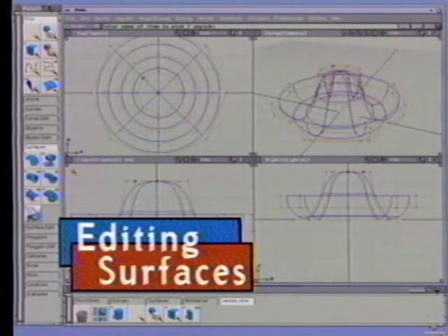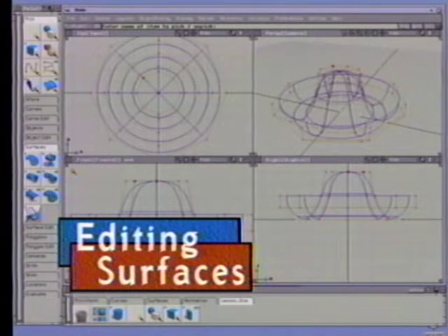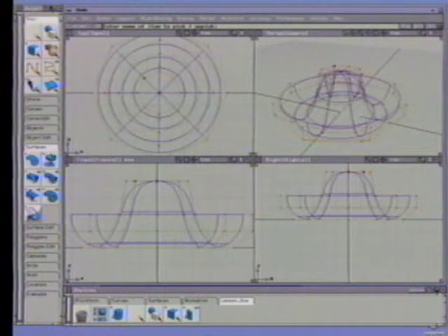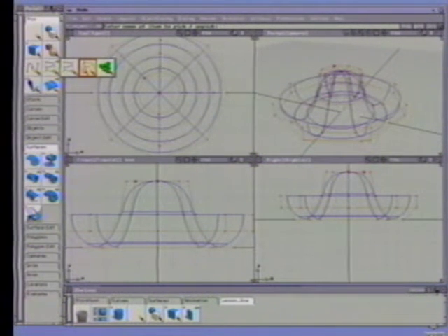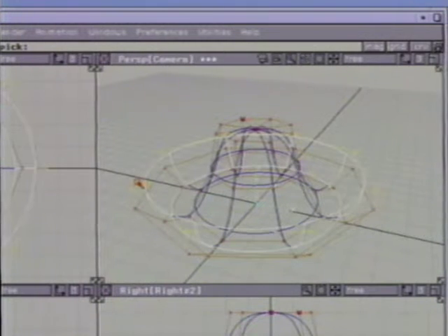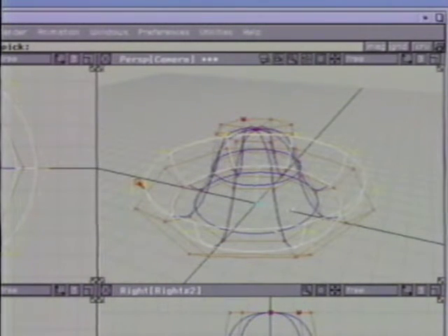Close the Control window. Earlier, you edited and refined the shape of a curve using the CVs. A similar technique also applies to surfaces. Select Pick Point Types Hull. In the perspective window, click on the hull at the outer rim of the hat with the middle mouse button. Note how all of the CVs connected by this hull are picked.